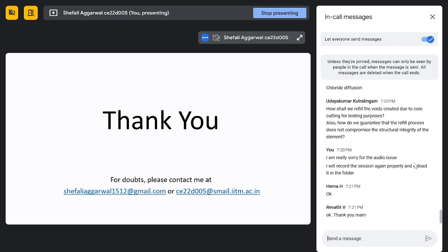In case you are not getting any kind of deterioration in there, and you want to just fill that core, then you should know what the parent concrete is made of, and you should make sure that your fresh concrete is almost similar to the parent concrete. It should not be much different from the parent concrete. And then there are some bonding agents which are used before concreting in such cases also. Some chemicals are used as a bonding agent, so we can use those.